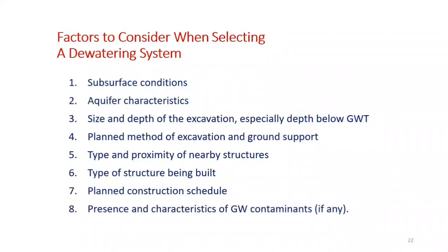Yeah, a very important factor, which is that if you have some kind of contaminants in the groundwater, especially if there are some kind of industries, or maybe some landfills nearby. If you have some landfills or some kind of industry which is producing some contaminants, and you do excessive dewatering, then these contaminants or the leachate from the landfills can move to the construction site, or you are actually causing them to move or mix into the groundwater. So that can also cause serious environmental issues. So that's why it will again depend on what type of system you are using for dewatering in such situations.